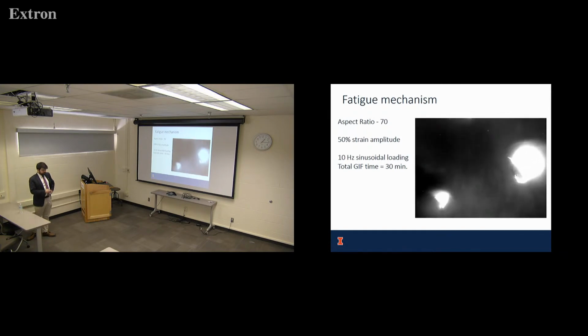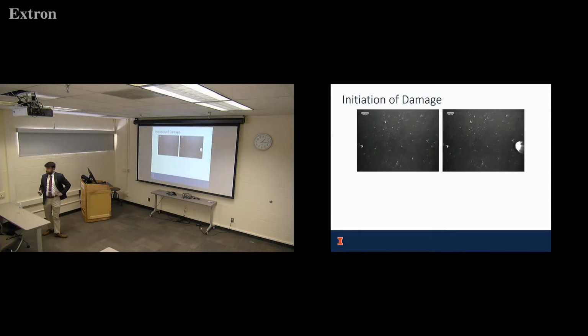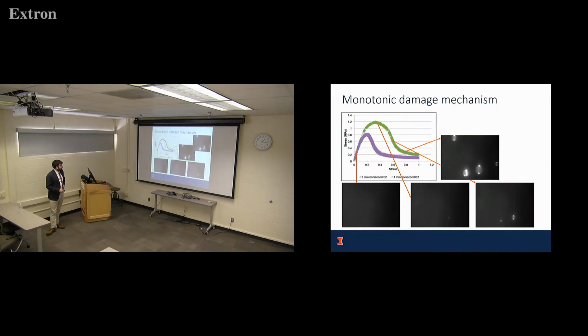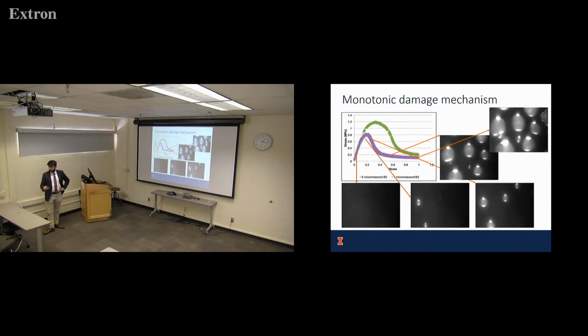Yeah, we did. Actually, one thing we looked at, it's in the paper, but it's not in this presentation. One thing we looked at is, once we start to see many cavities form, and it's in our paper that was in IJPE last year, with the growth rate. So we started to characterize each cavity that we could see fully in an image. We characterized the rate of growth and when they're forming, and this actually helped us to separate into that 3-stage model, but also to verify some of the theory that had been seen in other materials.